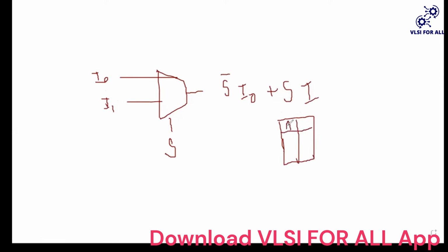Now we have to implement NOT gate using mux. We have an input A. When its value is 0, the output is 1. When its value is 1, the output is 0. So what will I do? We took select line A.